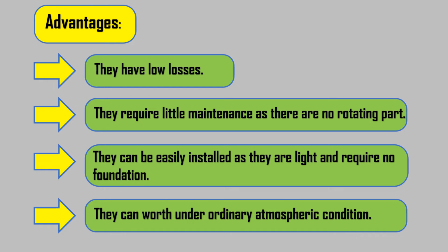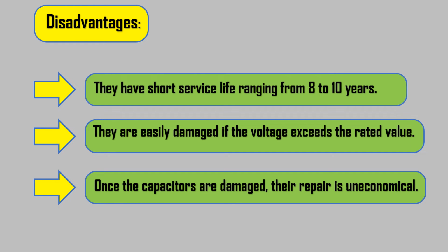Though it has advantages, yet it has a few disadvantages. Number one, they have a short service life ranging from 8 to 10 years. Number two, they are easily damaged if the voltage exceeds the rated value. Number three, once the capacitors are damaged, their repair is uneconomical.